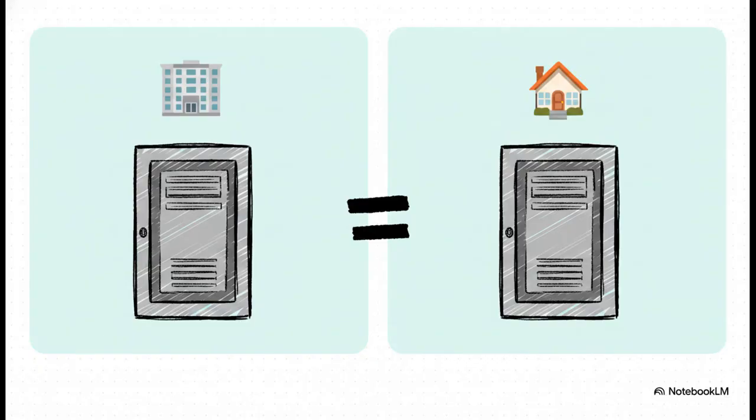Oh, and before we move up the chain, we have to bust a major myth, the whole load center thing. You're probably wondering, wait, where does a load center fit into all this? Well, according to the NEC and UL, there is zero difference, literally none, at the code level between a panelboard and a load center. Load center is really just a residential marketing term used for lower-cost consumer-grade panelboards. When you're dealing with commercial specs, always use the proper code terminology, which is panelboard.